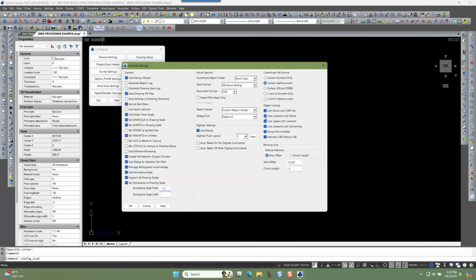Because this particular linking is one directional, meaning that if you change the point location, the line work will update. But if you change the line, like just do a grip edit of the line, it will not pull the points with it. And in fact, anytime then you come back into where it has had to have refreshed from the coordinate file, then it's going to change that line back to what it was. So we'll see that effect here in a minute.